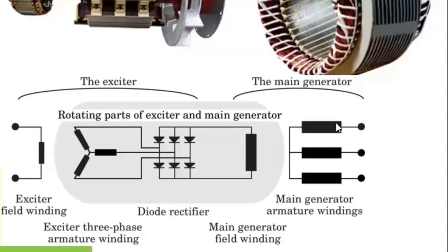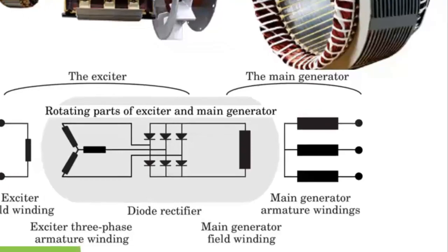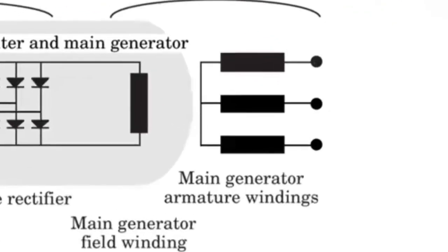If you are not getting equal resistance, it means that you have some challenge within the armature. Then if the start point, which is the neutral in this case, is included, maybe you have 4 leads out from your armature. In most cases, you will have 6 leads out.